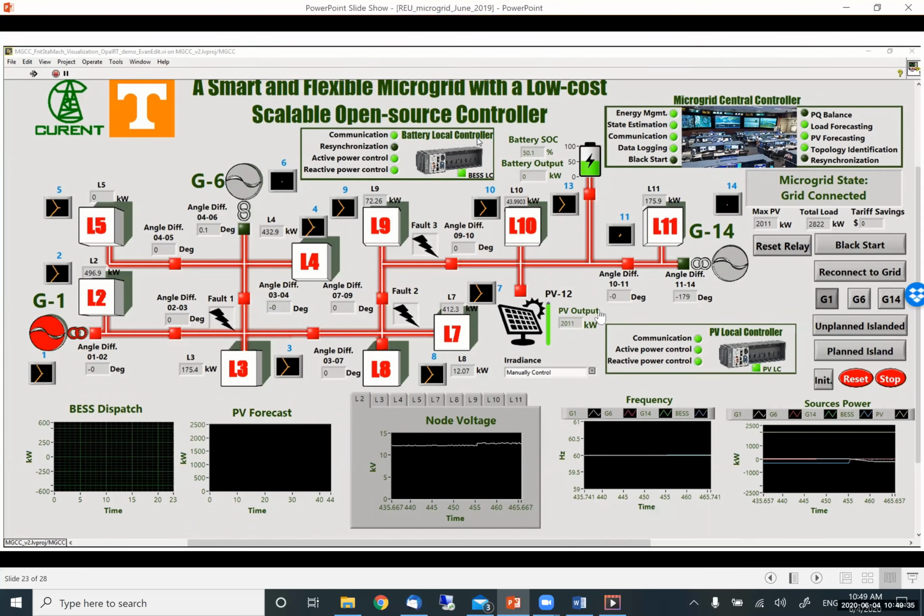Okay. So yeah, I think this is a very good question. The reason is that, for example, this is another feeder, and this is another normally open switch to connect this feeder to another feeder. And you can see the other feeder has its own power supply all the way along to here. If you close this normally open switch, then you close to another source.